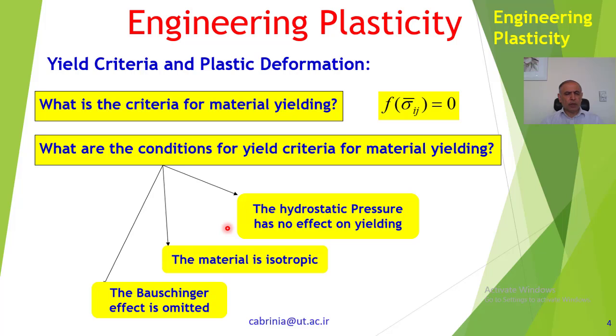And when you apply the load in the compressive direction after unloading, then these crystals with residual tensile stresses were under compressive stresses, so these compressive stresses cancel out those residual tensile stresses, and that's why the yield strength comes down a bit.